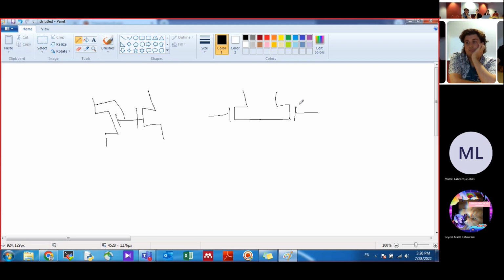The annoying part is that you should compensate and Cadence is not there for you. You should already know that there is a problem, because Cadence will not understand this effect, since those effects are for after fabrication, after tape out. So it's a tape out thing, not a design layout thing.